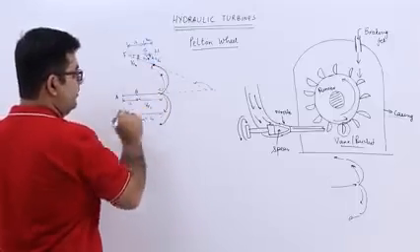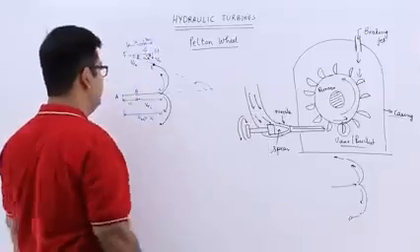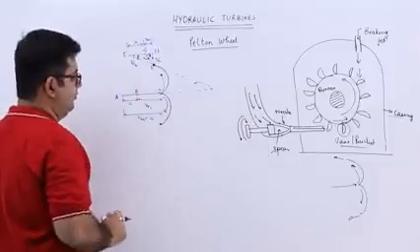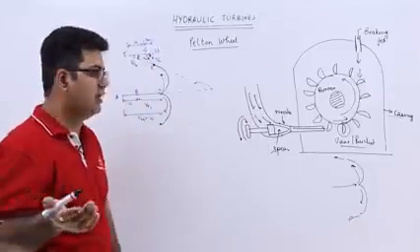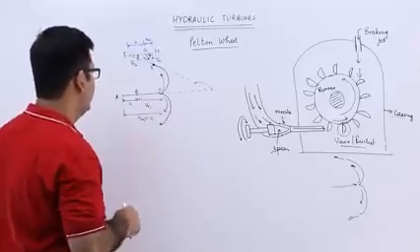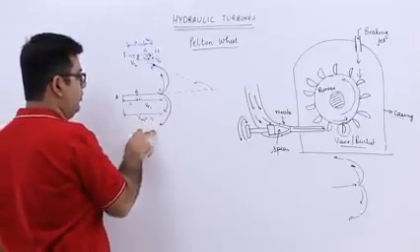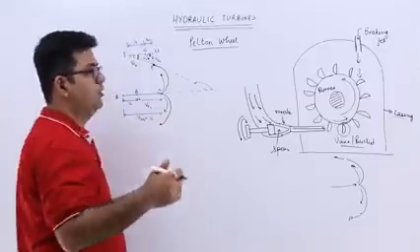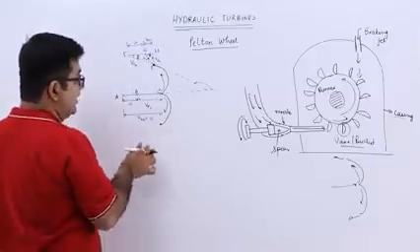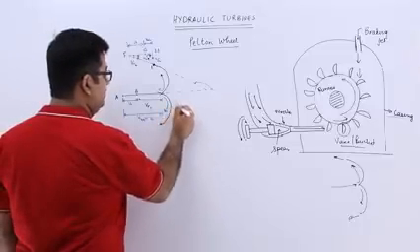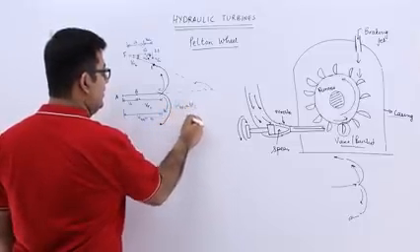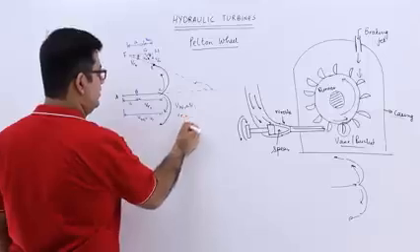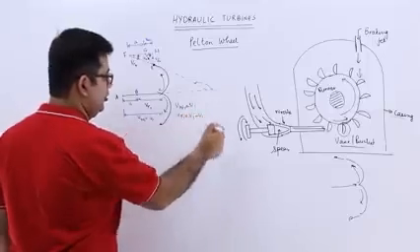So this is the bucket from this point to this point. You have the jet coming in horizontally. So you don't have your IVT. Basically IVT is nothing but a straight line in which you have U1, VR1 and VW1, and VF1 becomes 0. So for the inlet velocity triangle, I can say that V1 is equal to VW1 and VR1 is equal to V1 minus U1.